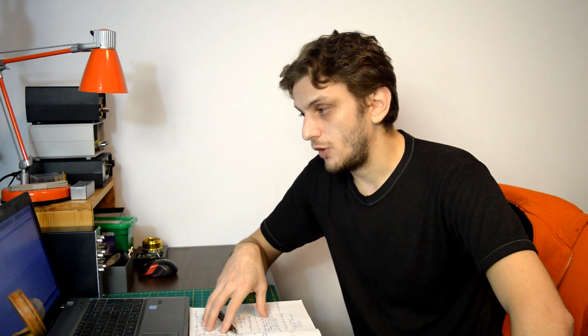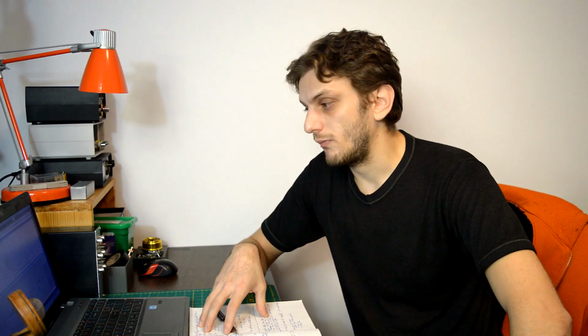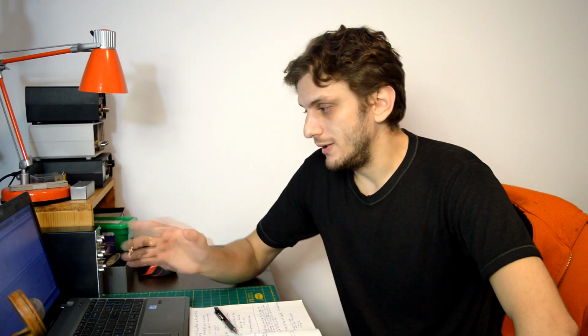So in general, if you want to reduce your output noise, you need to choose smaller resistor values. That way you will reduce the thermal noise they're contributing. You can reduce the bandwidth of your amplifier, but that's not always acceptable. Or you can use low noise parts. And in this case, the LM2902 is not a low noise part.